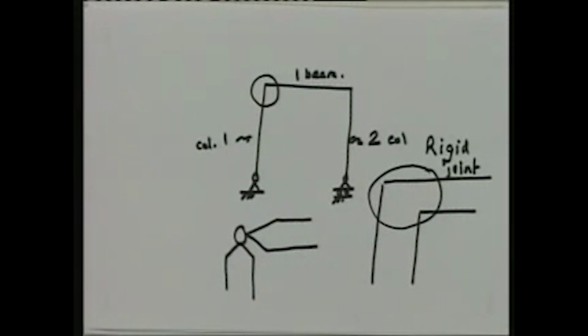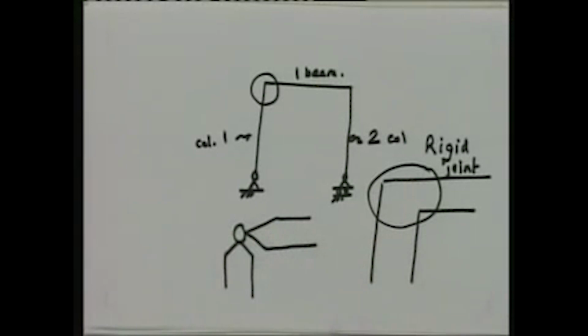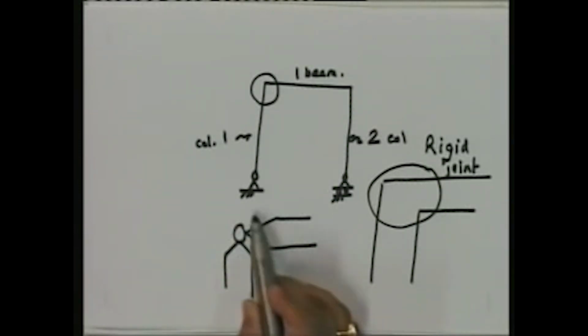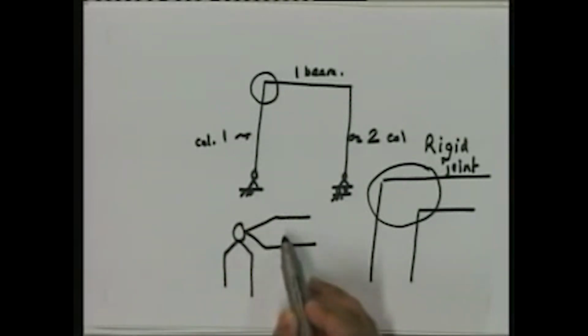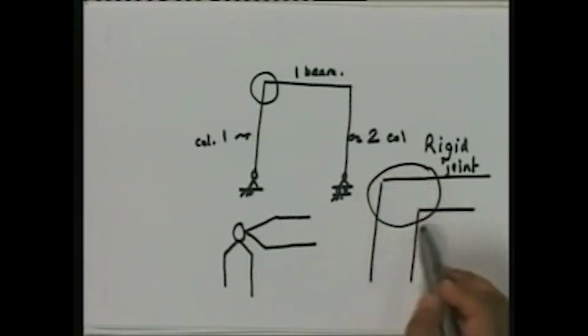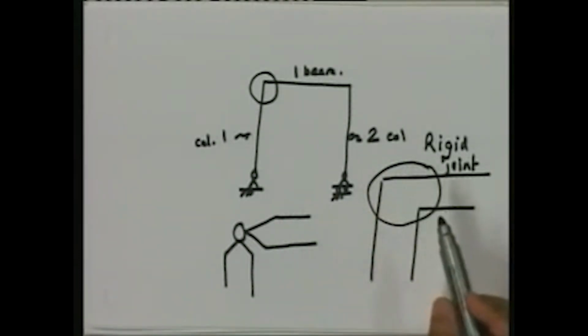This is what a joint looks like. This is a pin joint, and that is the reason why in a truss, since this joint cannot transfer any flexural forces, the members become axial members. Whereas in a plane frame, this joint is a rigid, continuous joint. And because of that, you can transfer both forces as well as moments at the joint.